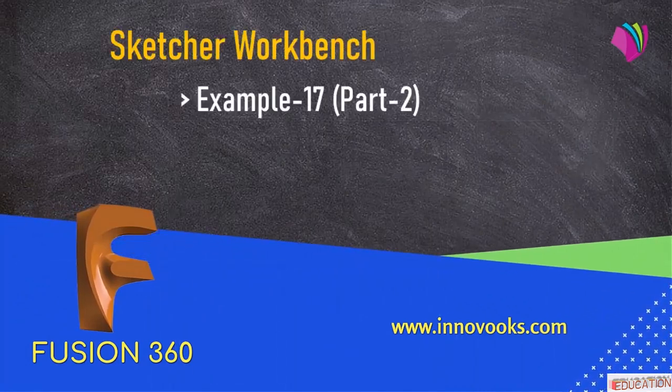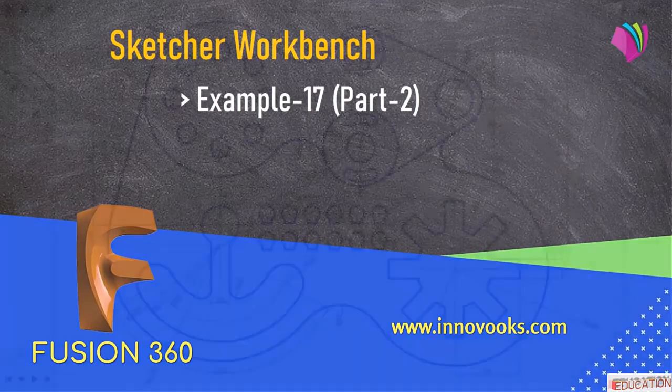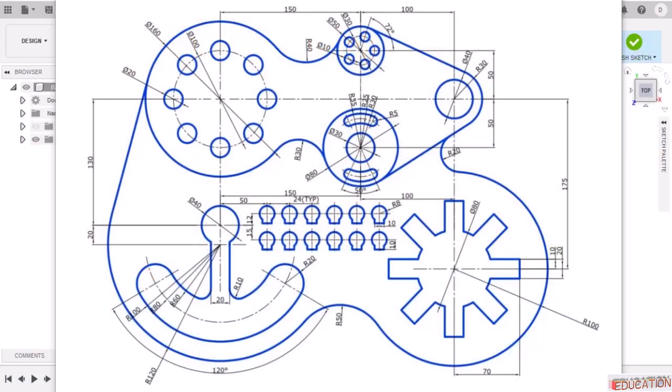This is the continuation of the last lecture. In the last lecture we had done example 17 and we had created this upper portion. In this video we are going for this lower portion. For this lower portion also, first we are going to create this outer boundary and then we are going to create this inner stuff. Let us start by first creating this circle and constraining it,